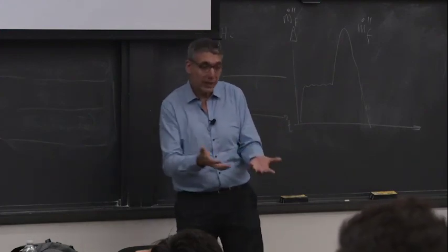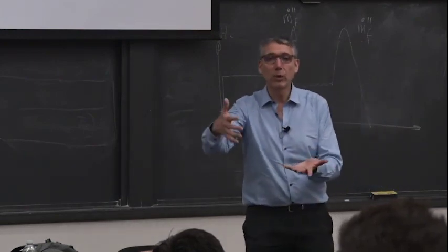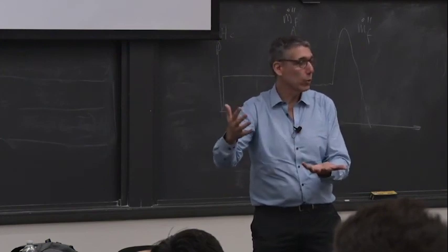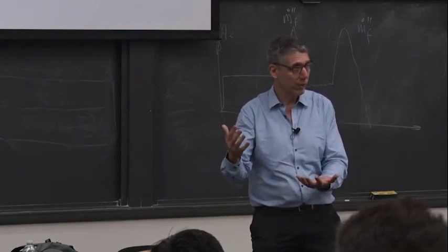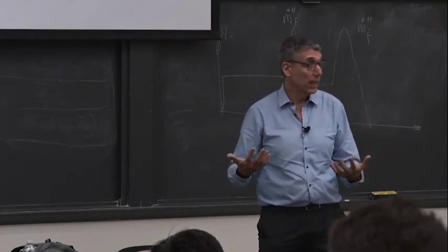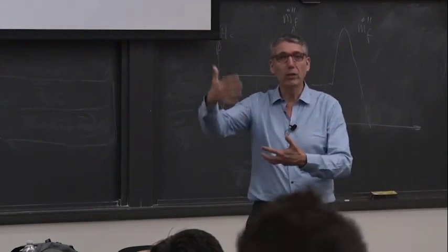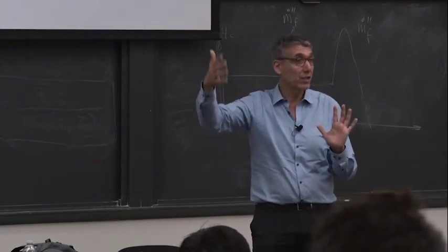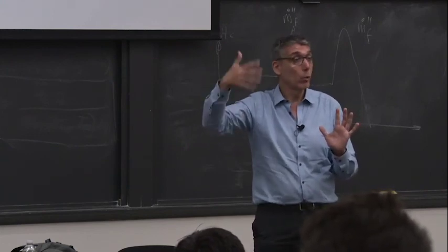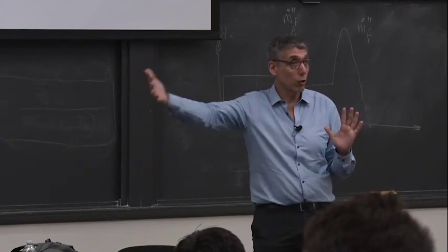Okay, so effectively we've walked through the whole problem of life safety, and we are at the point where we have flashed over. We understand the limitations of what we're doing, we understand the coarseness of what we're doing, we understand the variability and where things are coming from, and we can create a story that more or less brings me to the point of flashover and the end of the life safety problem. Is that okay? So what comes next? My room has flashed over, I have a fully developed fire, and I need to be able to address the structure.